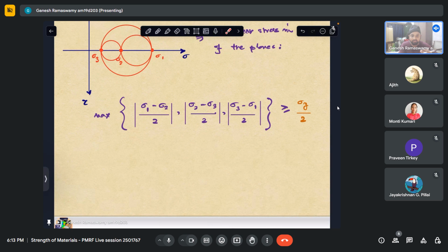And then we have the component made of certain material, which based on testing we have found fails at some sigma y, the material parameter that we have. And this theory states that the material is deemed to have failed when the absolute maximum shear stress exceeds that for this material in the case of uniaxial tension. So this is our maximum shear stress criteria, also known as Tresca criteria.